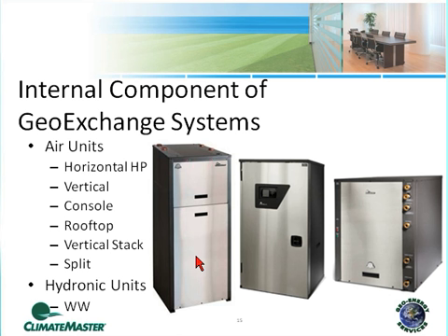So it's becoming more and more popular here recently because engineers find this a little bit easier to swallow, if you will, if they're not familiar with the ground source heat pump technology. They're a lot easier to adapt to just taking the boiler and chiller out of their existing projects and putting in a bank of water-to-water heat pump units. The next unit here in the middle is what we call a high-temperature hot water unit.